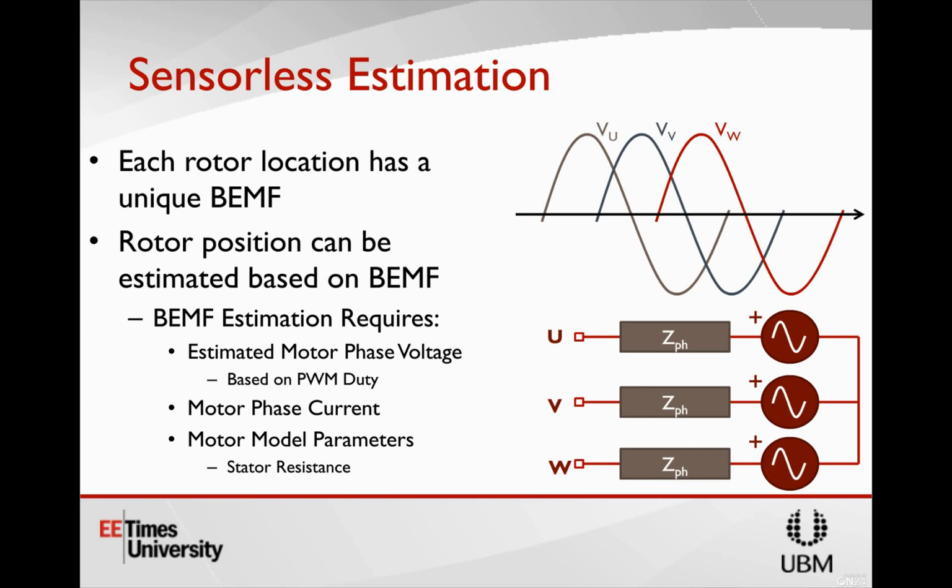Okay, thank you. Let's do one more question and then we'll end it. Here's one from Asuk. Do we need to protect the input pins of the difference amplifier due to the voltage transients across the phase? You'll usually have inline resistors to help protect the circuitry, but they shouldn't impact the signal you're getting out of the voltage drop across that resistor. You will tend to want to put resistors in there just to help protect the op amp.